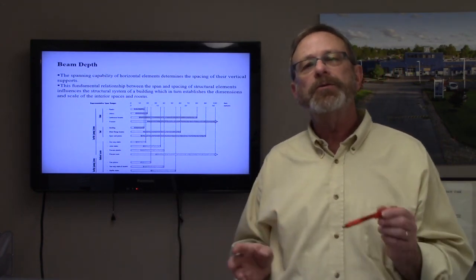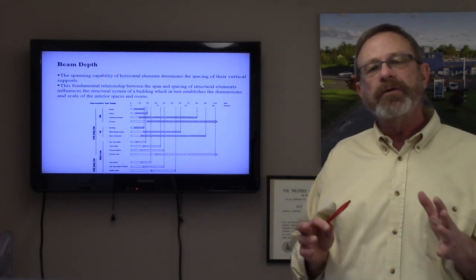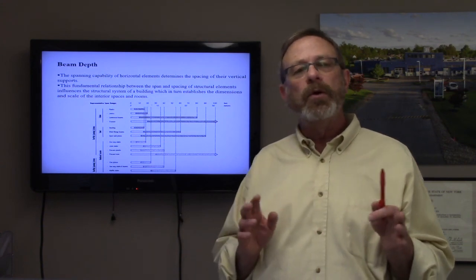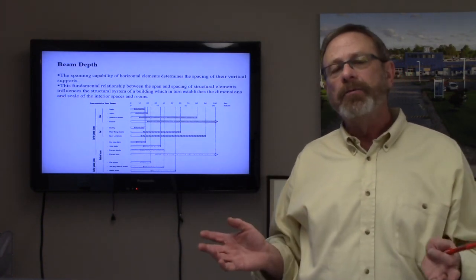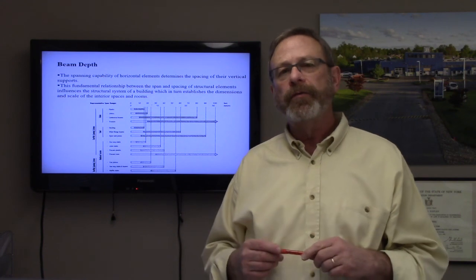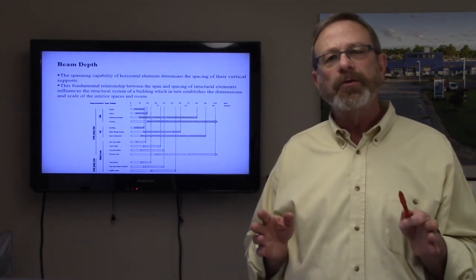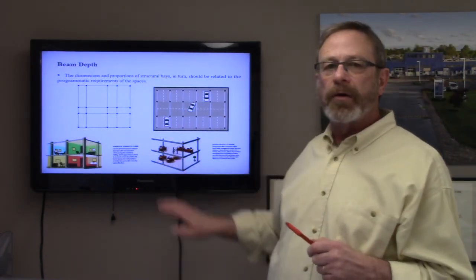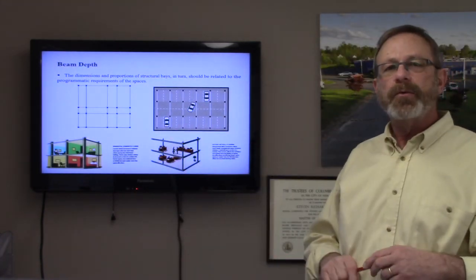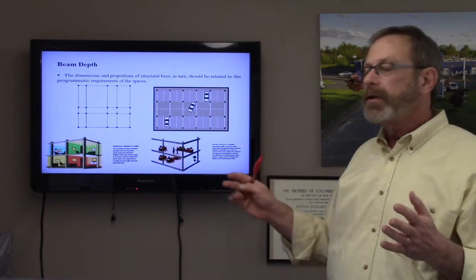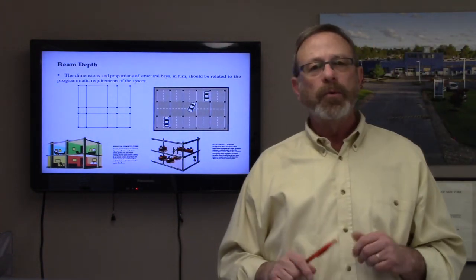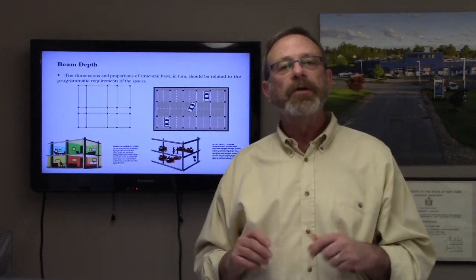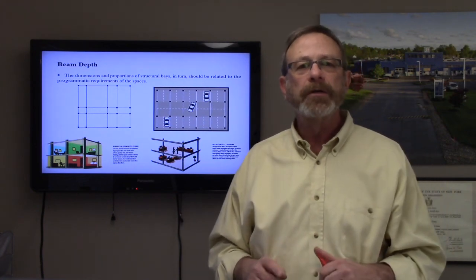So the spacing of structural elements gives an organizing pattern to the structure, and you might use it to organize your walls and partitions. Or you may not. You may choose to ignore it and work off of that grid. But in any event, the grid is going to be there because it's needed structurally. You can see in this case a parking garage level with the columns spaced where they need to be to support the building, but it's important to understand that there is an organization to the building which you can use as a benefit or a contrast.